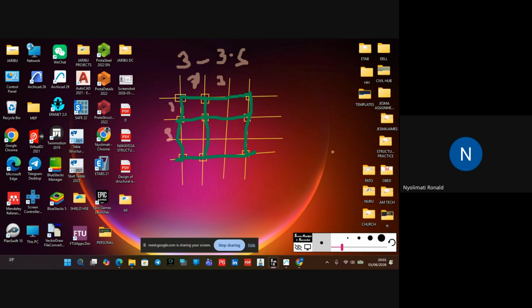So also put in your mind, they are saying the span of beam in Eurocode, the longest span of beam should be 6 meters. Okay, the longest span of beam without a column, the one which is running from 1 to 2. For example, a beam running from this point to this point, the maximum should be 6 meters.